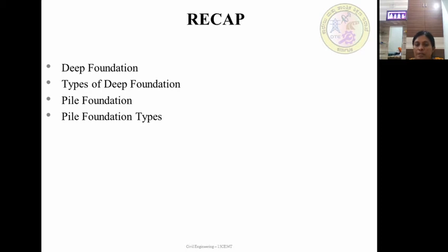Timber piles are usually the cheapest type of pile and take very small load capacities compared to other piles. Steel piles are used to carry heavy loads, and increasing their length can be done easily. In composite piles, cement, steel and timber can be combined.